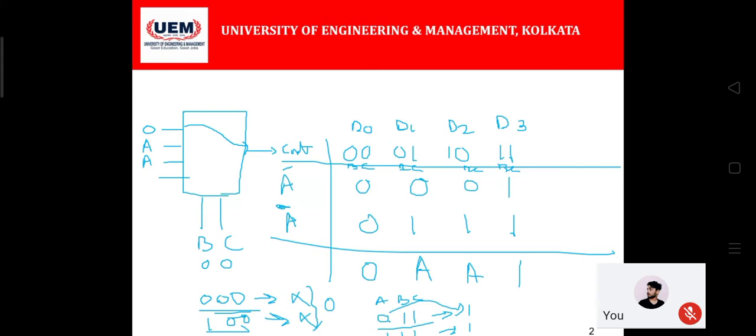You can see it is converting from 0 to 1, and it's directly moving from 1 to 1. So though there is no conversion, one thing that is very strict is that the output always becomes 1 whenever B and C values are 1. Irrespective of the values of A, whether it's 0 or 1, that does not matter. When B and C are 1 and 1, we get to see a carry getting generated. That's why the fourth value will be directly providing a value of 1 to the fourth input of the multiplexer to implement the fourth term and the eighth term in our truth table.